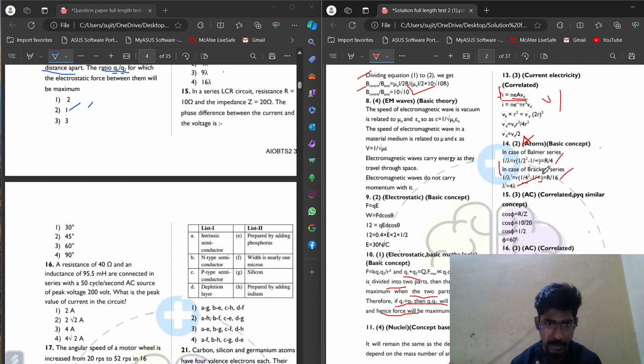In the power factor formula, the power factor is given by cos phi, that is, it is given by resistance R by impedance Z, right? So R is given already, and I told you the formula of Z, that is equal to root over of R square plus (XL minus XC) square, where XL is the reactance for the LR circuit, and XC is for the CR circuit, right? So just put the value, and here you don't even have to know the formula.